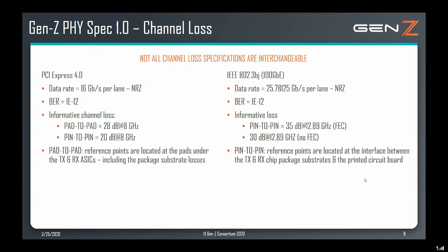So when you're sending the transaction across the 4 lanes, a little like PCI works, the packet is striped across the 4 lanes. So you get the bandwidth improvement of having 4 lanes running simultaneously, but also because you've striped it, your transaction time is 1/4, because 1/4 of the packet is going across each lane. So the bandwidth implications here are, the wider you go, the better for higher bandwidth and also faster transaction times across the channel. The trade-off being that with more PHYs and more lanes, you use more power. So hopefully that addresses the question a little bit.